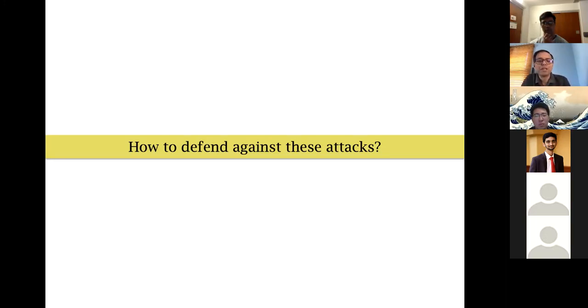Because for the microphone, the signal is very weak. Before amplifying, the low pass filter will not work very well. But for the speaker part, we can use a high pass filter. Correct. If you can buy that speaker, you can definitely do it. But what we used was a regular ultrasound speaker that you can buy for $1. It's not easy to get high pass ultrasound speakers in general.